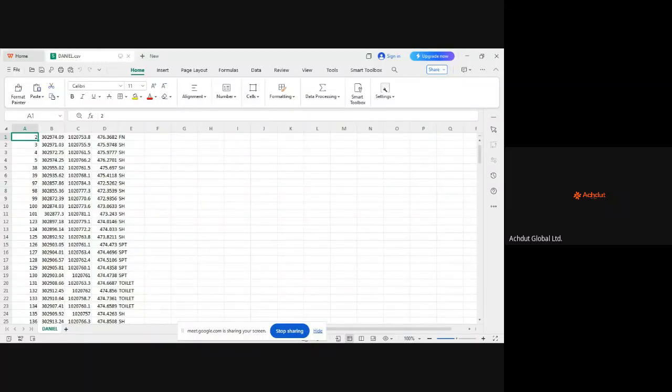That's just to mention. So you have your eastings, your northings, your height data, and you would have spot height, spot height, spot height, if you've been on a topo project or probably just randomly. Spot heights are just random points that you pick in a topo survey.